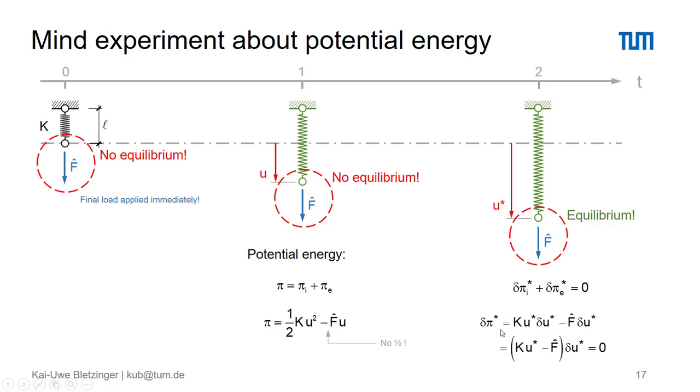And the last thing I would like to comment is that in the final state where the virtual energy is 0, this is already satisfied by the equilibrium equation, what you see here in the bracket, that is 0 already, which means that the choice of the virtual displacement in the final state is completely arbitrary.